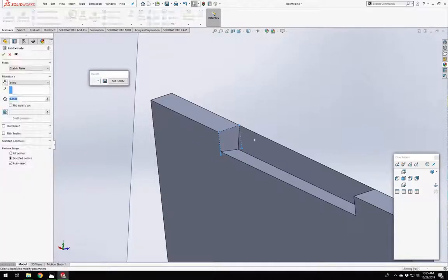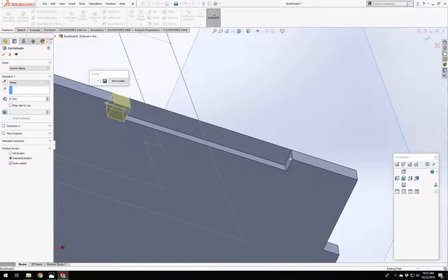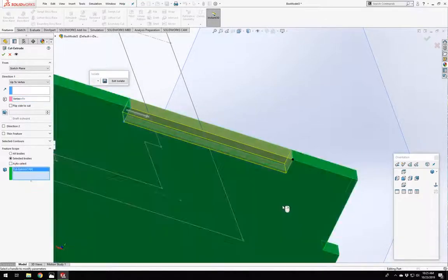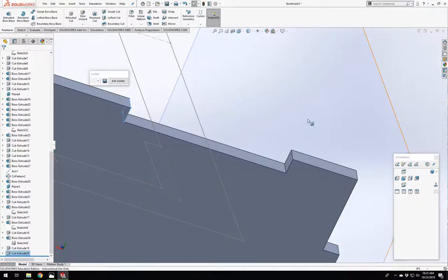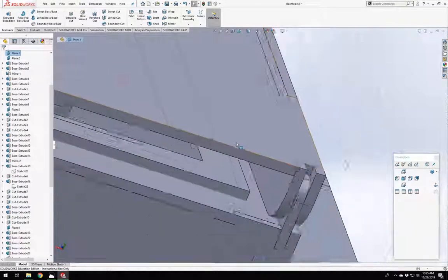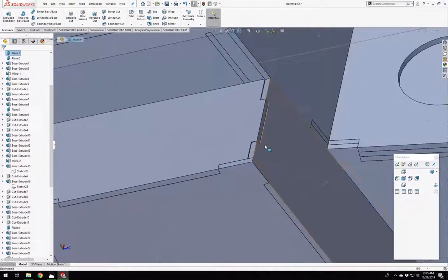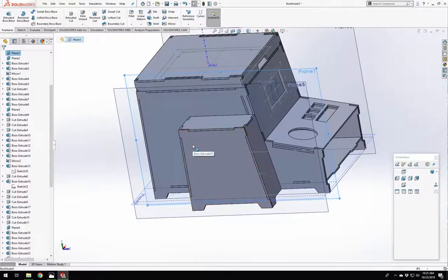And we can do an extrude cut just from this face to that point. Just that body, making sure. There we go. So now that's correct, and we can exit our isolate. And now we're back, and now that looks correct. All right, so let's save.